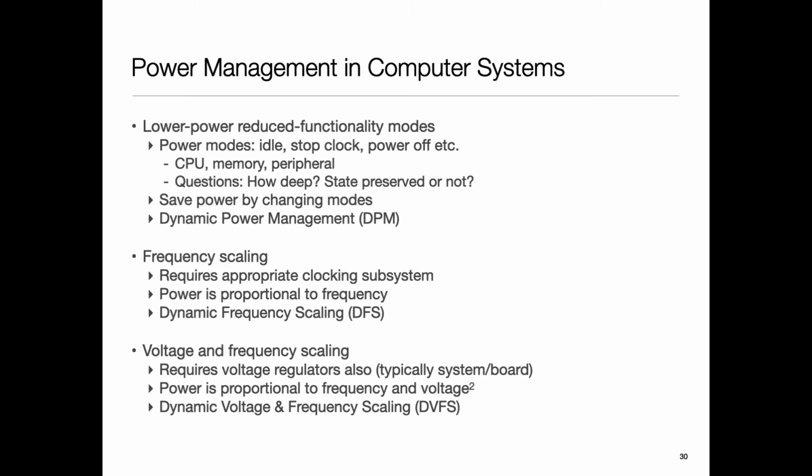It sounds easy, but it's super hard. The reason is this mapping between frequency and voltage depends upon temperature, and depends upon the specific chip. I take 10 copies of the same processor, you're going to see differences. So there are special circuits that people put in to figure this mapping out for that particular piece of hardware.